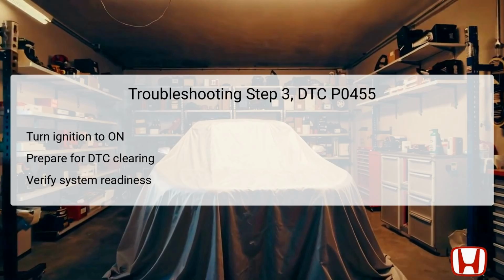By enabling the onboard diagnostics, the vehicle's module can prepare for any further testing that might be required. After the ignition is in the on position, you should be ready to proceed with clearing any existing DTCs to ensure you start fresh with diagnostic assessments.